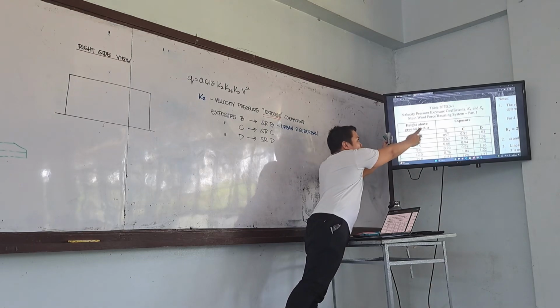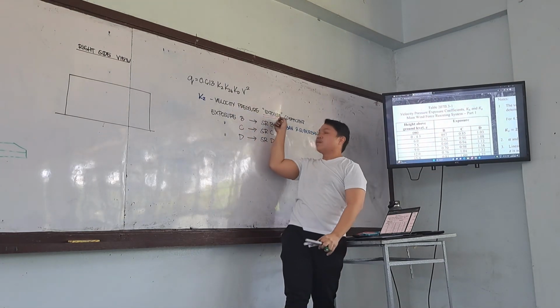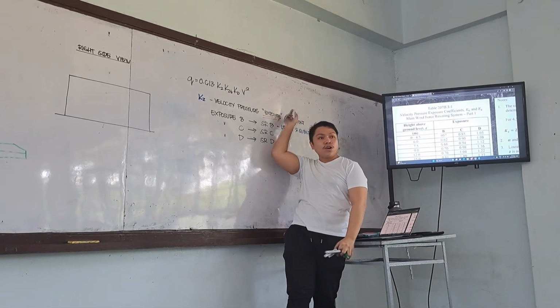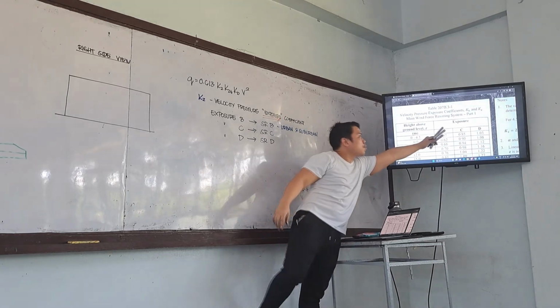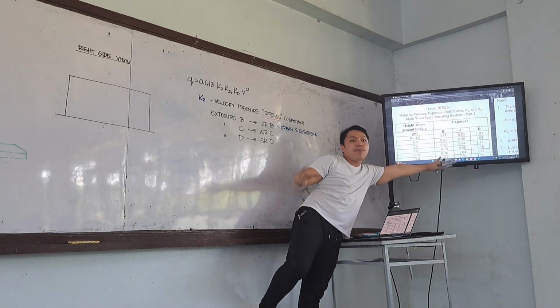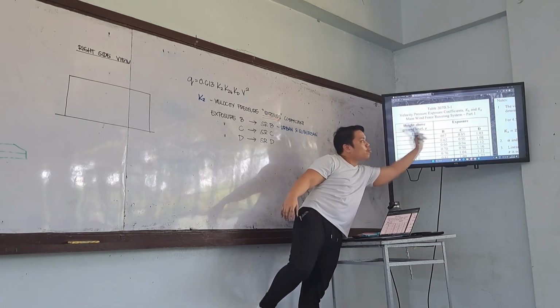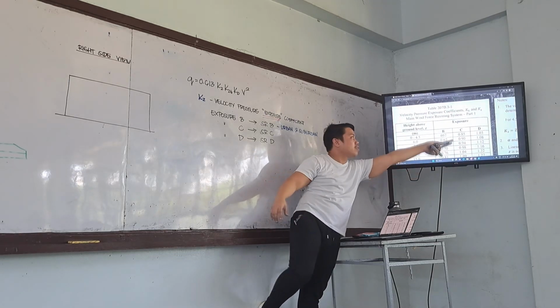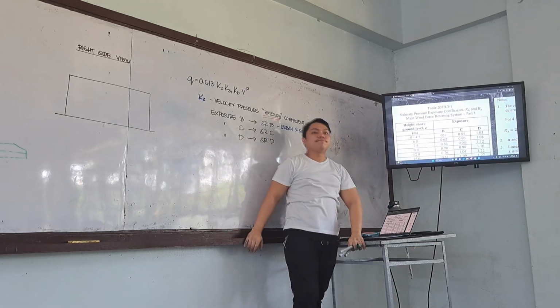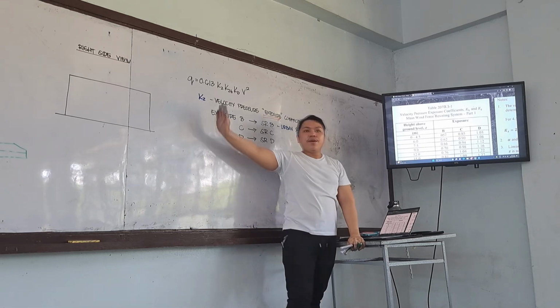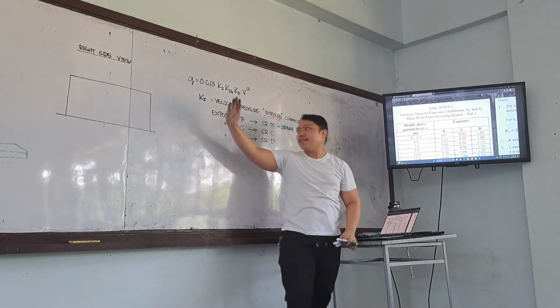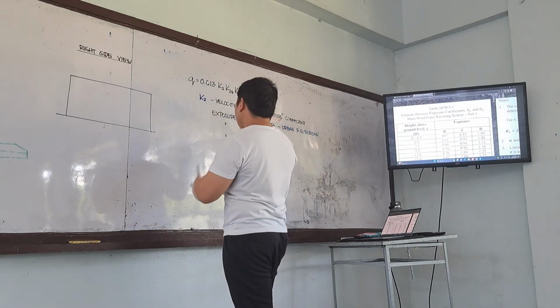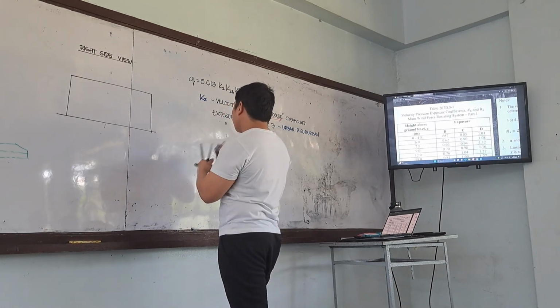This is the importance of our velocity pressure keyword and exposure coefficient. If your exposure is B, your Kz is smaller, because there are many obstructions. As you go towards open exposure, your Kz becomes larger. That is the principle. Let's proceed. Kzt. What is Kzt?